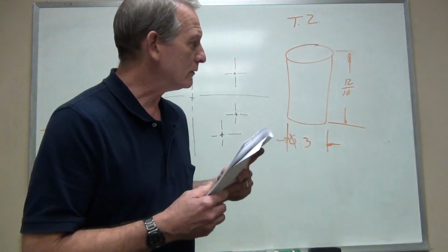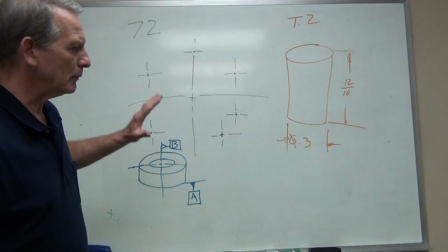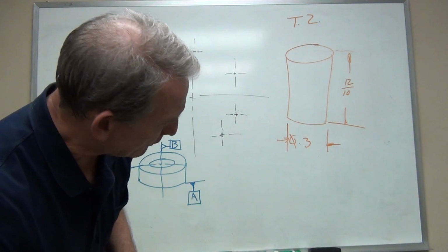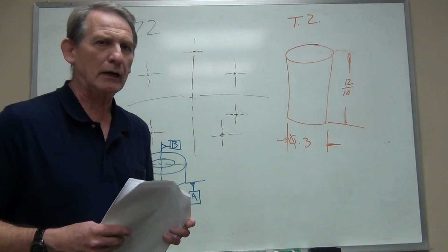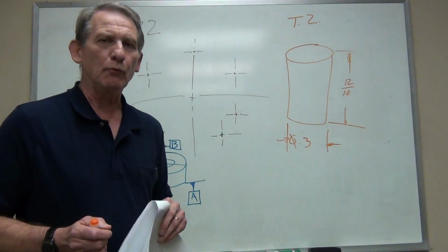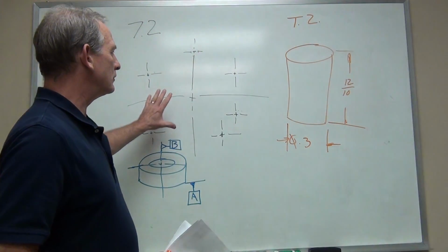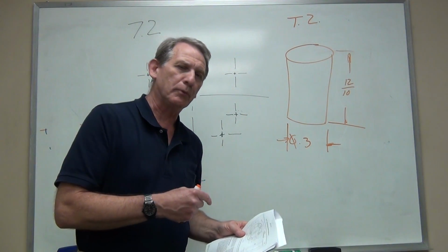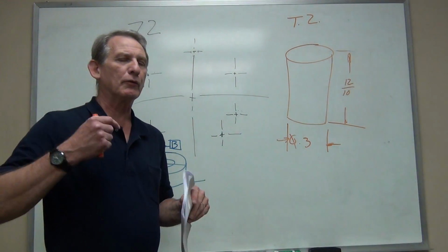And with those holes stripped away here, I hope it's a little bit easier to see that what we are defining on this ring are cylindrical tolerance zones. And once we have this perfect geometry established, now again I don't have all the dimensions there, but each one of these locations is located per figure 7.2, and those are perfect locations.